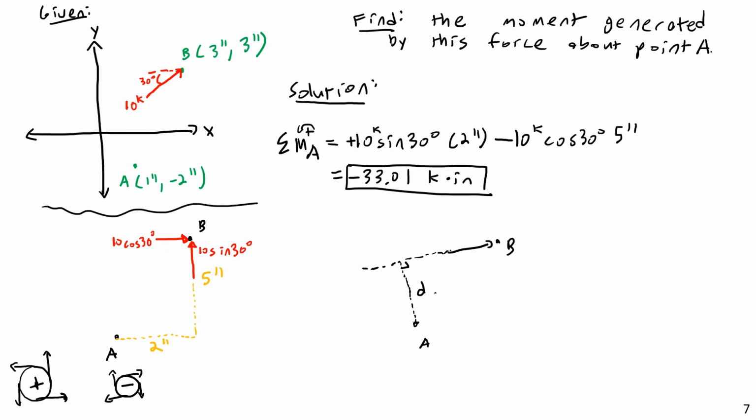I don't usually do the perpendicular distance even in 2D problems, because honestly, most of the time it's just not worth wrapping your head around the trigonometry. Usually it's a lot easier to break the forces down into perpendicular components, or into their x and y components, and then use the x and y coordinates as perpendicular distances.